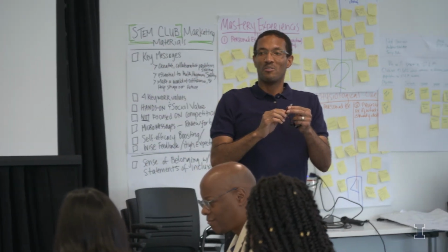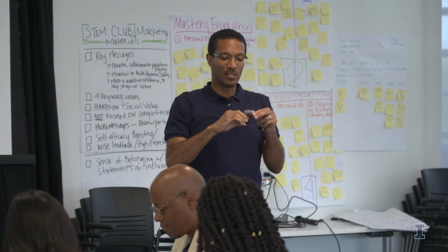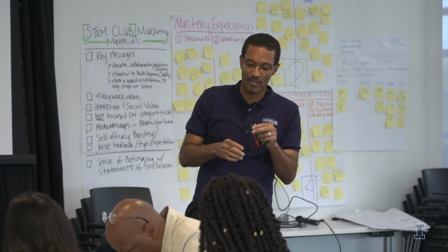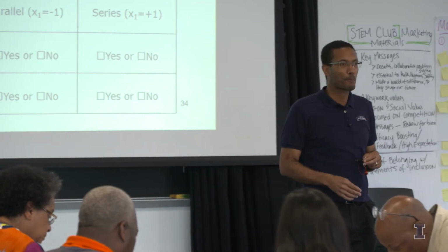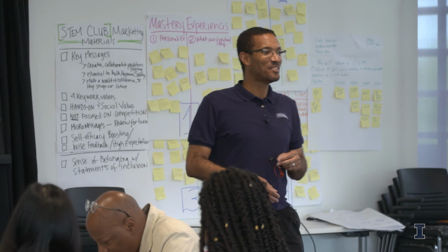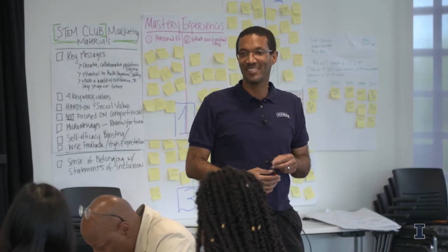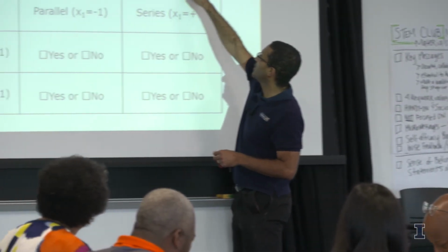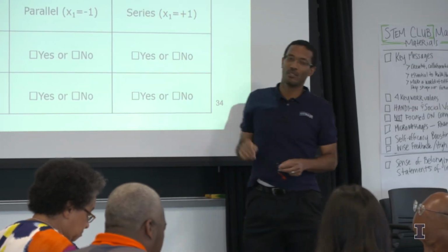Okay, so once you've gotten that one, swap and do black to the short leg, and red to the long leg, and see whether it lights up. That's this condition. So we just switched the red and the black. So red to the resistor, black to the other leg.